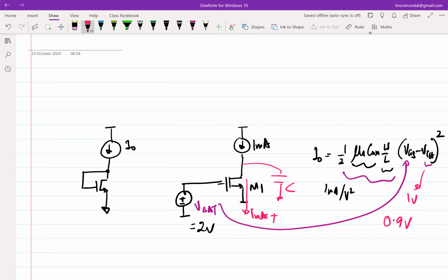Threshold voltage decrease. So threshold voltage decreased by 100 millivolt. If threshold voltage decreases by 100 millivolt, approximately how much will the current increase? Why 0.01? Huh? It will be quadratic. So you will expand this term. Why will current reduce? Threshold voltage has decreased, right?